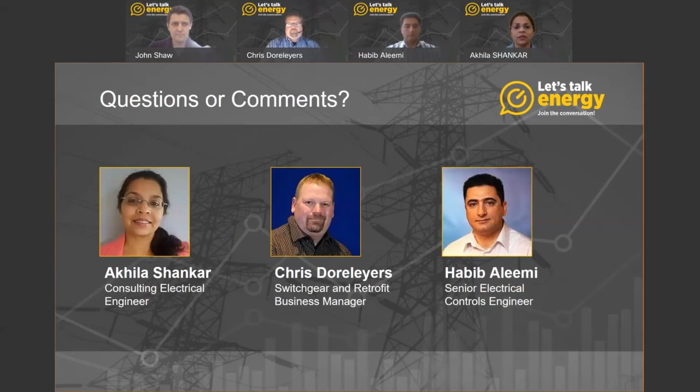The main difference between a standby generator and a prime rated genset comes from the number of hours the units are operated in a year. While the prime units run for anywhere from 10 to 15 hours per day, the standby gensets will run only a couple of 100 hours per year. So the chances of failures are higher in the case of the prime gensets because of the higher usage.